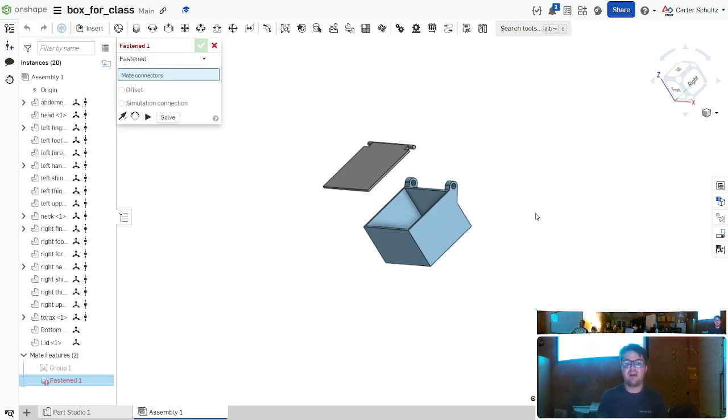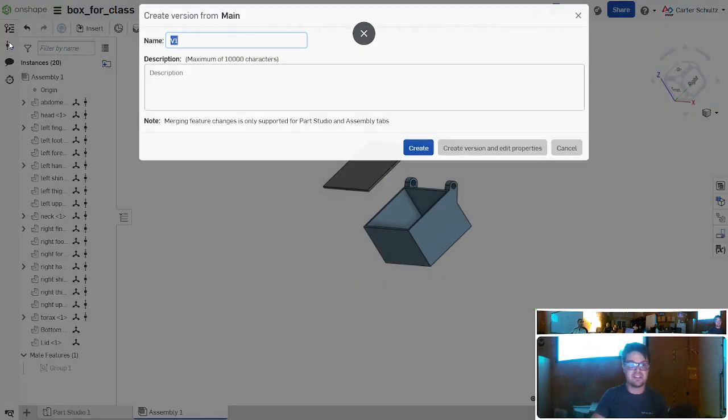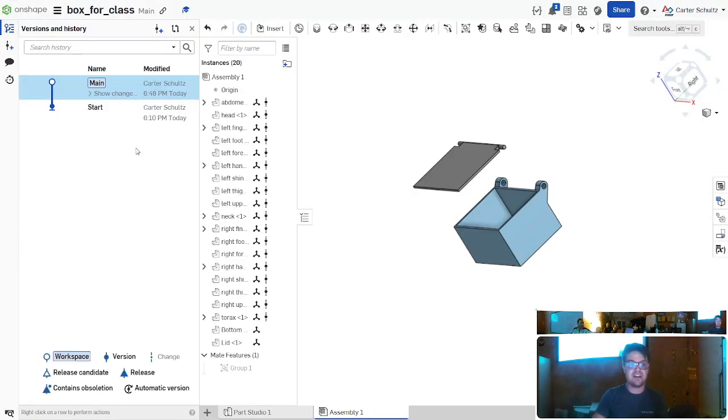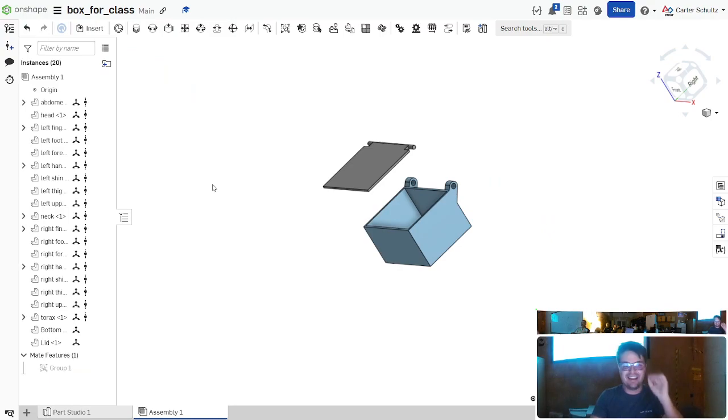Yes. Okay. And a crazy thing that happens with OnShape: as I added that dude's human in, I'm actually versioned from this other document. OnShape has an absolutely ludicrously good version management system. We haven't gotten into this yet, but there's an entire Git branching workflow to branch versions of a model, merge versions of models back together, and choose what parts of your models are updating from other parts of models, so that I can pull a part into my assembly directly, fully linked, or I can pull a version of that part from a point in time into my assembly. If you look at this, there's release candidates and, holy crap, if you used Git for software development, you'd love OnShape. Mechanical engineers don't know what they're missing, but sorry, that was a bit of a tangent.